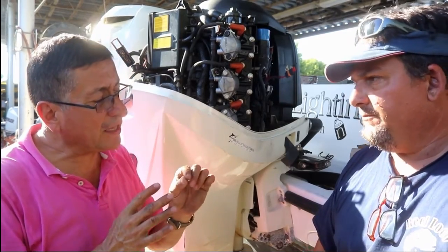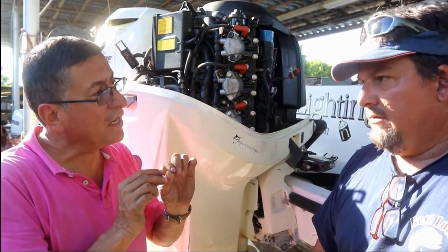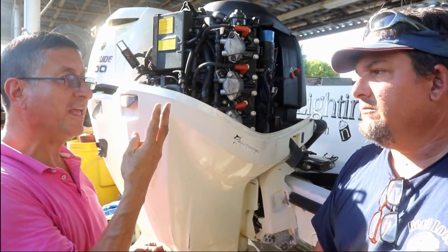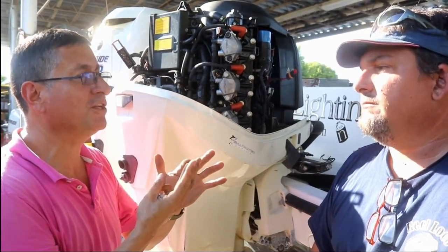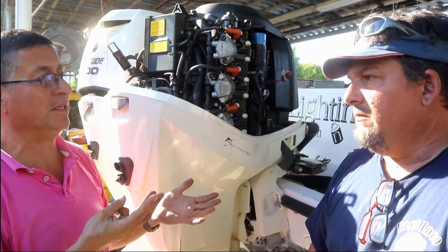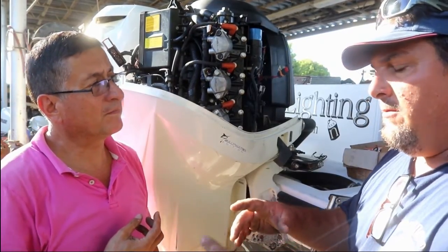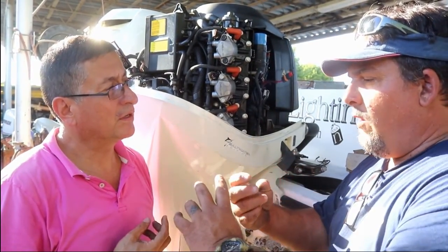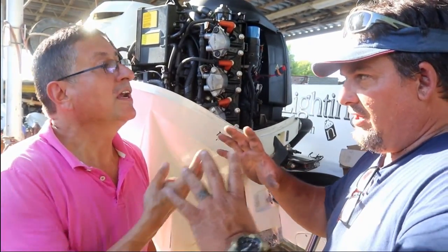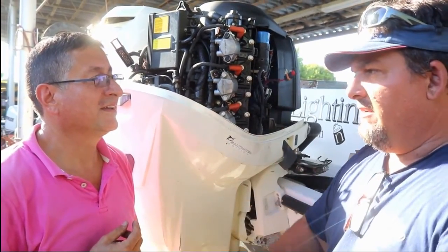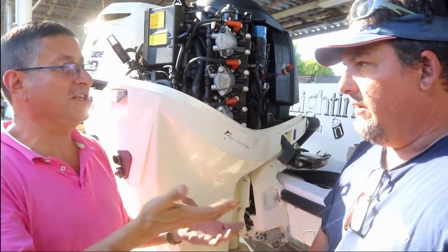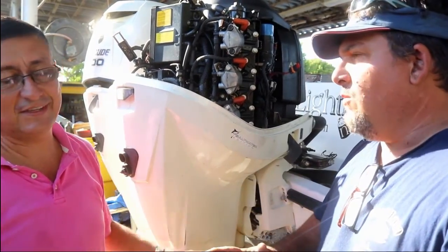Correct, because you cut the cable for each sensor, and you now have the wires free to check voltage, to check resistance, whatever you want. Not only that, you can make a system that hooks everything up, and the wires are spliced out, so the system is actually connected. And you can physically see how it's running and test it while it's running. And you can test the voltage without probing any wires or anything.